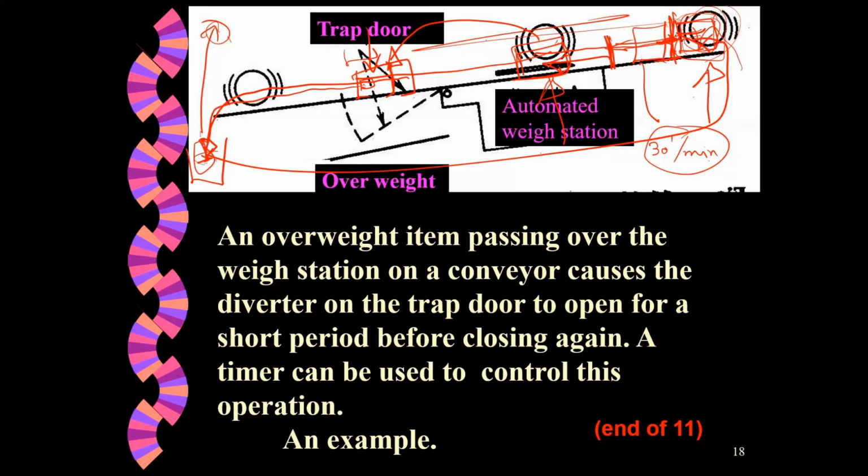So what happens when the pot drops onto the weigh scale? You have a dynamic load, sometimes 1.2, sometimes 1.3 times the actual weight, due to dynamics of being dropped or swept on top.